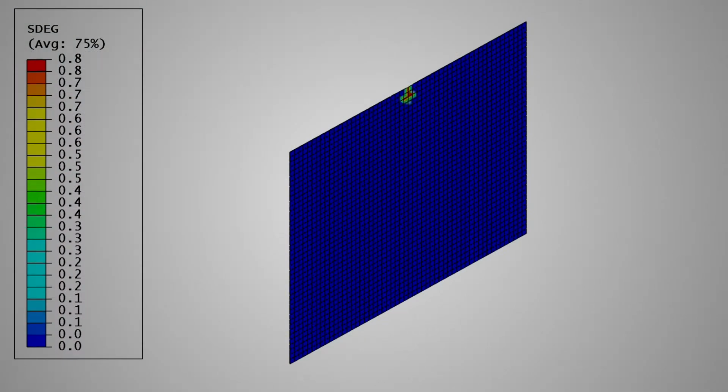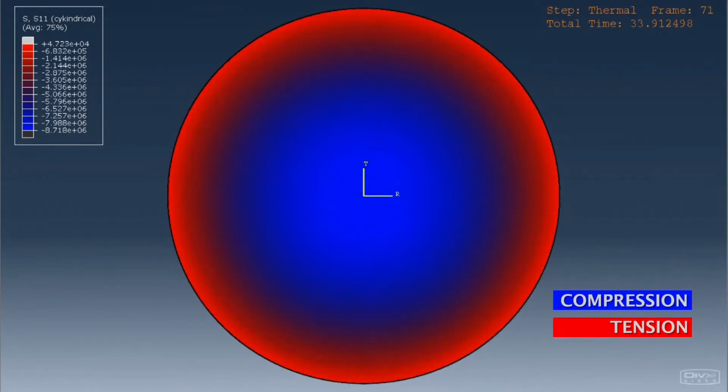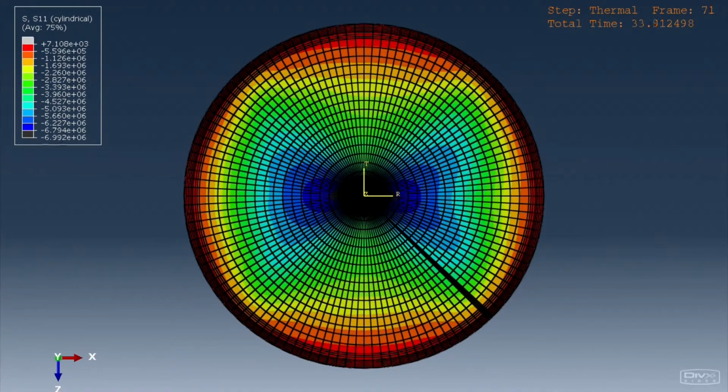So within this project, we have used finite element modeling in two ways. One was to calculate the stresses around cracks and see how a crack initiates around an indentation, how it evolves. And a second big work that has been done with finite elements deals with the furnace. So we were modeling the furnace, we were modeling the wafer inside the furnace and the temperatures within the wafer during a heat treatment.